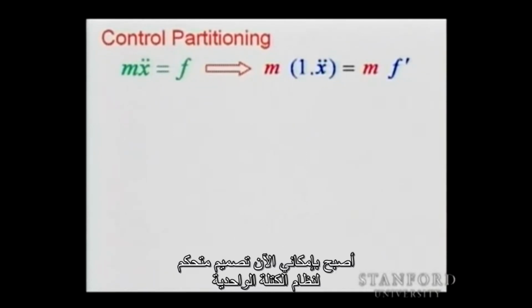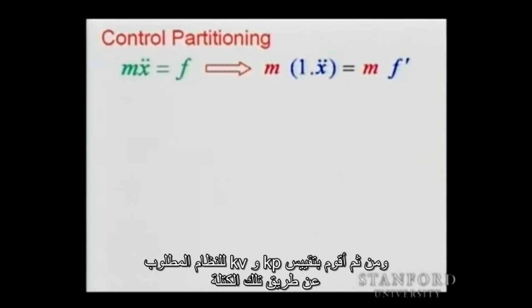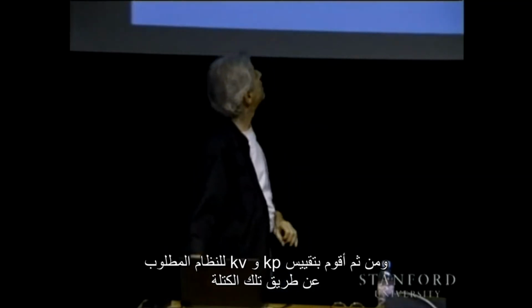So I can now design a controller for the unit mass system with Kp prime and Kv prime, and then the Kp and Kv for the original system will be just scaled by that mass.